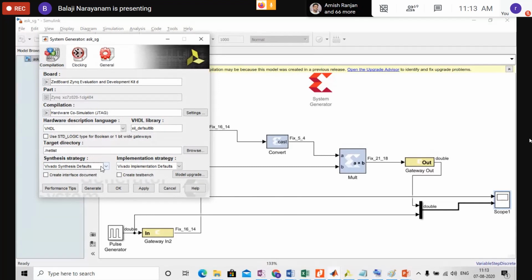That's it. So I need not worry if I am not aware of these steps. These are very simple steps in the design cycle. Once again: manipulation, synthesis, translation, mapping, placement and routing, and finally bit file generation, programmable memory generation, hex file generation, with which I will program my FPGA.